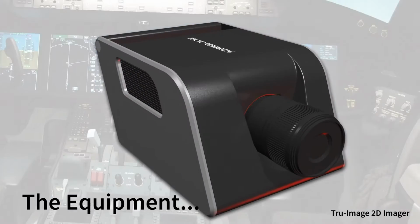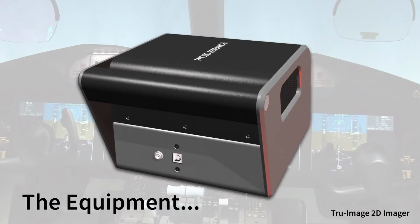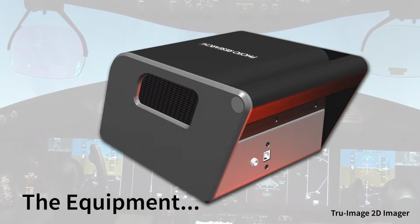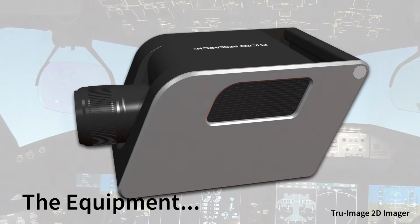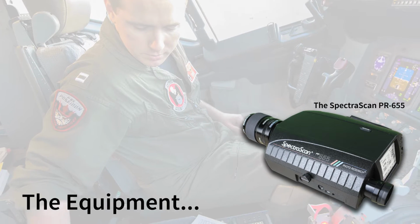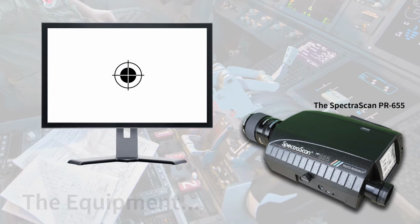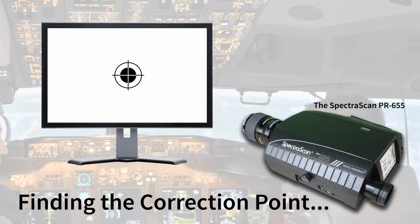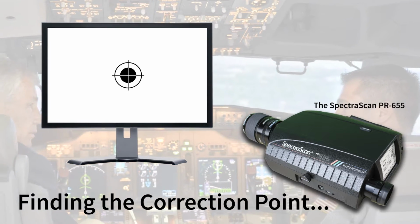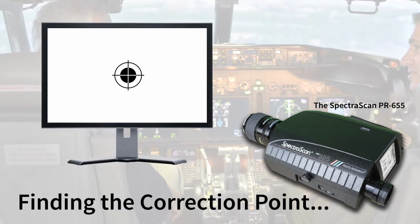In addition to the Tru8, we need a reference instrument for independent measurements capable of measuring CIE XYZ tristimulus values. Ideally, this would be a calibrated spectroradiometer such as a Photo Research 6 series or 7 series. We also need the display with the image that was just measured by the imager. The goal for this step is to determine which part of the image to measure with the reference instrument.